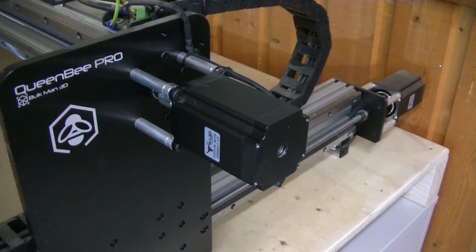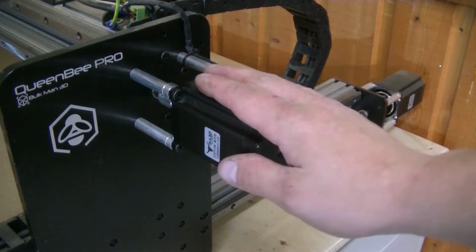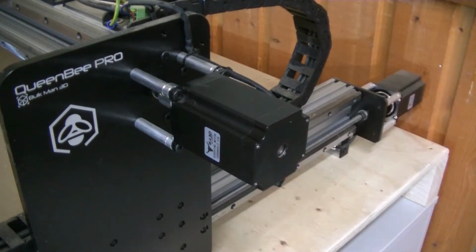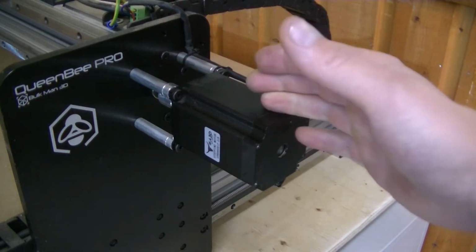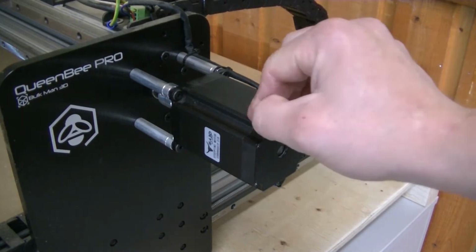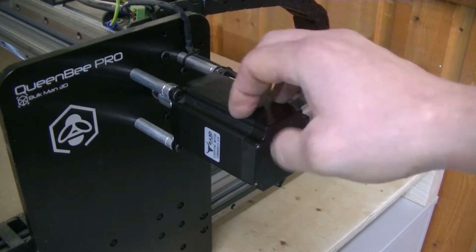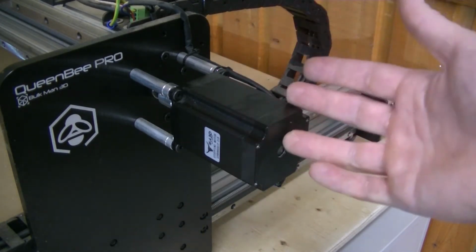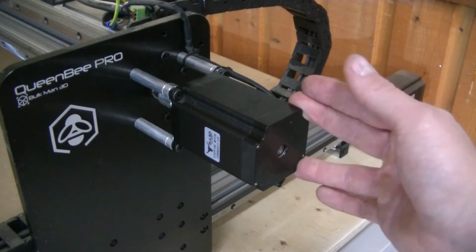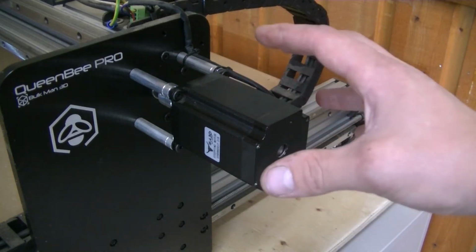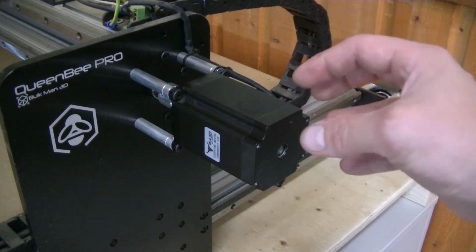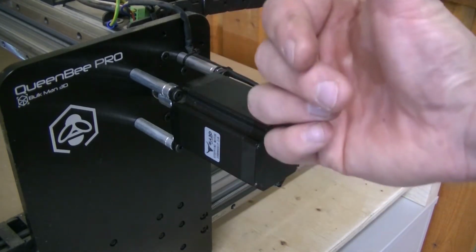This is a stepper motor. It's one of the most cheap and easy ways to achieve really precise motion in home-built CNC machines, or any other type of machine of your choice. This is also a DC motor, but of a completely different kind from the one I showed you right now on the bench. And the difference is that they don't contain any brushes. Now there is also a type of motor called a brushless DC motor, or BLDC, and they share some characteristics with the stepper motors, but there are also some important differences. Let me show you on the bench.